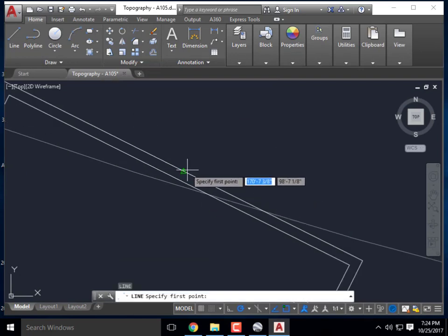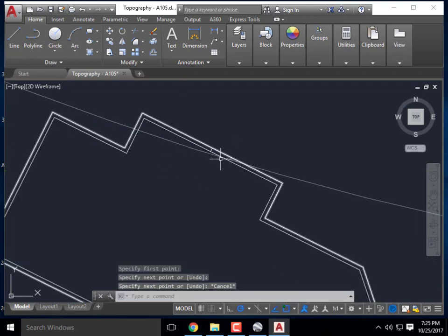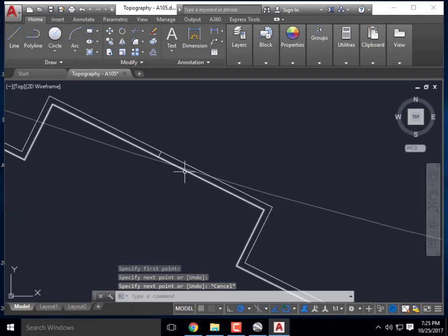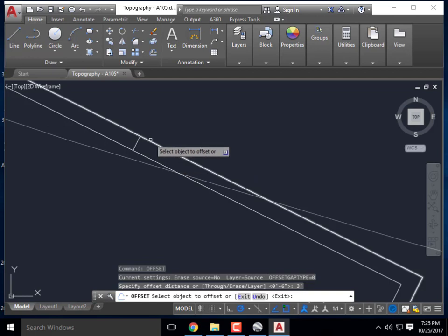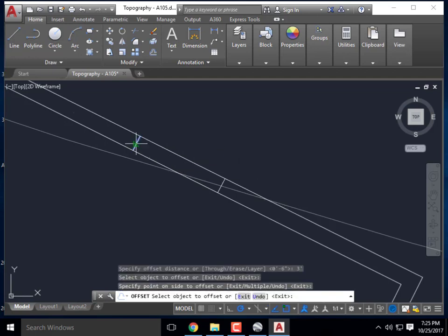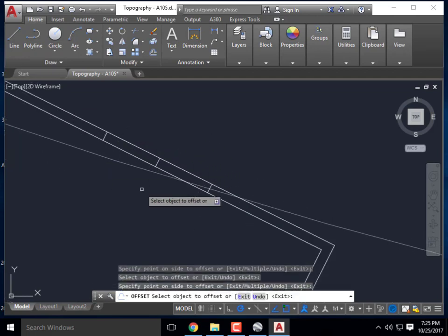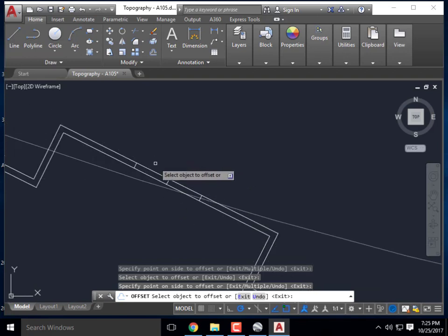What we're going to end up getting to is the group command. I want to show you how to group a selection of objects, so that once you create something like a door, you can easily copy it as one item and move it around to all of the other places. So let's make a 6-foot opening in our door. That's the center of my wall. I'm going to offset that line 3 feet. That's going to be the opening in my wall.